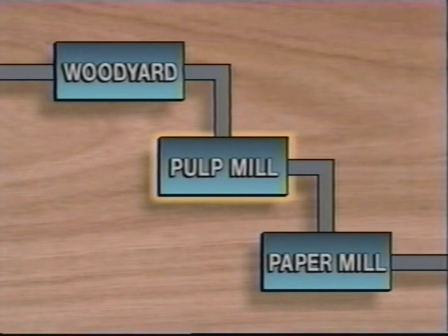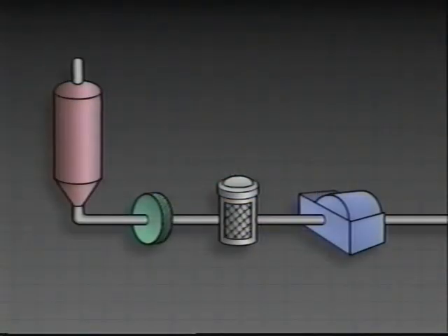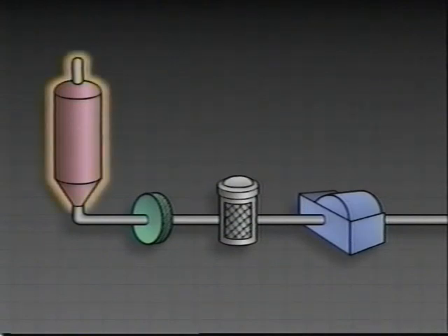There are different types of pulping processes. The type we'll be dealing with is called the kraft process. Let's see basically how this process works. The first of the major parts in this process is a digester. The digester is a vessel in which the wood chips are softened by a combination of chemical solutions, high temperature, and pressure. This process is known as cooking. In this example, the heat and pressure are supplied by circulating steam through the digester.